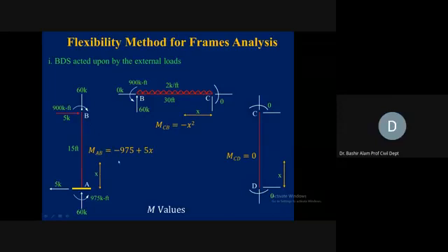Now taking AB, the vertical reaction at A will keep in equilibrium this 60 kip. So 60 in downward, so this 60 is in the upward direction. 5 kip is rightward directed, so 5 kip leftward directed, so horizontally this member is in equilibrium. Now moment: we have 900 in the clockwise direction, and 5 times this 15, which is also causing clockwise, so 5 times 15 is 75. So 75 plus 900, 975, is balanced by this 975 here. So this member also is analyzed and is in equilibrium.